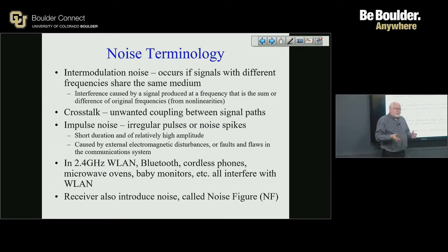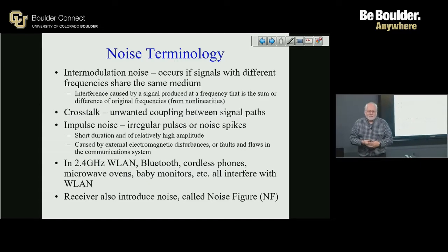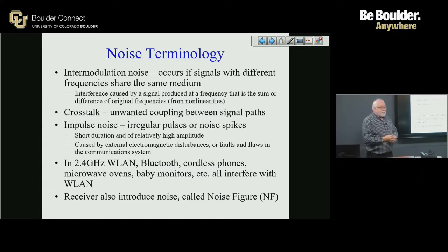So it's so funny to me to see people get really involved in all these hacks on Wi-Fi that try to do denial of service, when in wireless, really, to do denial of service, all you have to do is create enough interference that they can't close the link. That's a lot easier than trying to do fancy denial of service attacks. That means that if you're responsible for keeping a network up and somebody's decided to mess with you by putting some sort of noise source right near your receiver, then they can potentially shut down your network. It's not that hard.